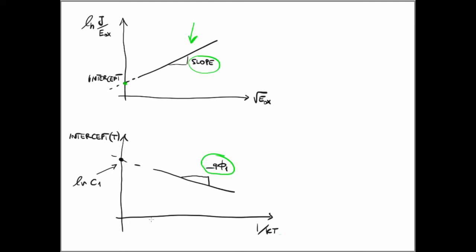So using these techniques that I've shown you, we can not only identify that in our device there is one specific conduction mechanism that is dominating over the other, but we can also be quantitative and actually say a bit more. So for example, in the case of Poole-Frenkel, we can say that the traps that are involved in this process are located phi1 below the conduction band of the oxide, and so on and so forth.